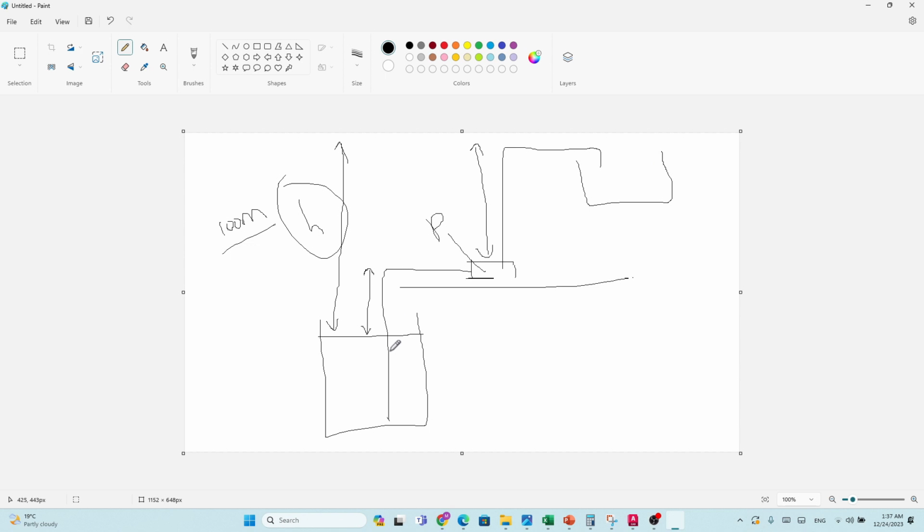Okay, so by transferring water from this point to this one, we have internal pipe flow, and due to the internal flow, we have friction, and it depends upon the type of pipe. If you have a very smooth pipe like PVC, you have low friction, but still you have friction to cover to move this water to this point. And another thing is fittings, these fittings.